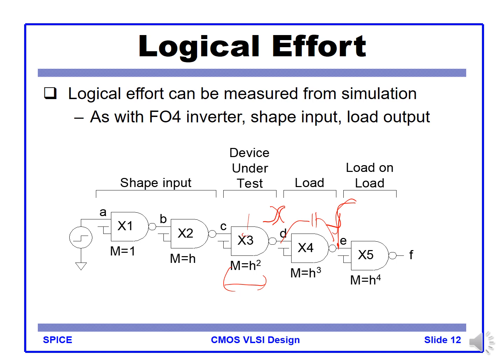So as you can see, whenever you build some test measurement, this is always very important, always model the input properly and output load condition properly. Without having input and output shaping blocks, you will get the wrong data, a wrong simulation result.